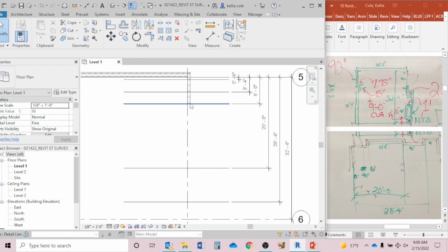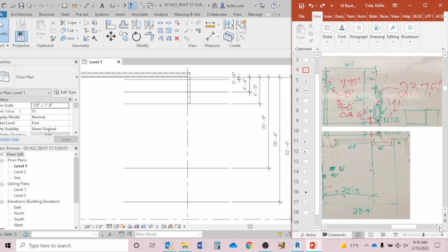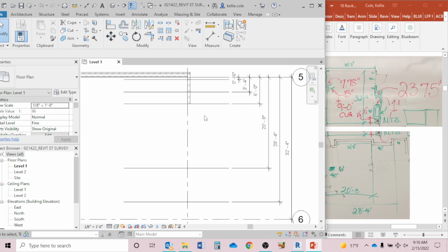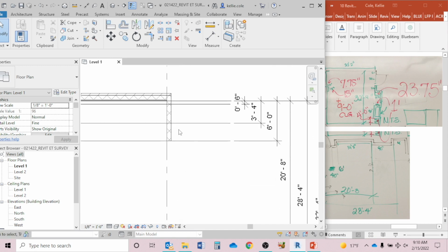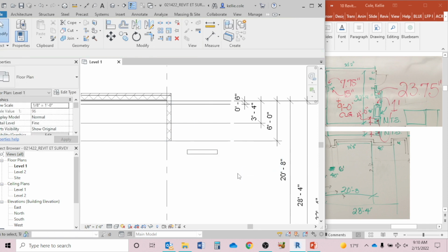All right, CMU wall also moves to the right if we're looking at the drawing. And our image says that that dimension is 23.75 inches. So let's draw a wall that's 23 3/4 to the right. That wall was also noted as CMU. I can type WA. I know that that wall goes in this direction. I'm just going to put my generic wall there first. And remember our match tool. MA. If I select the wall I want things to look like first, and then select the second wall, it becomes CMU.